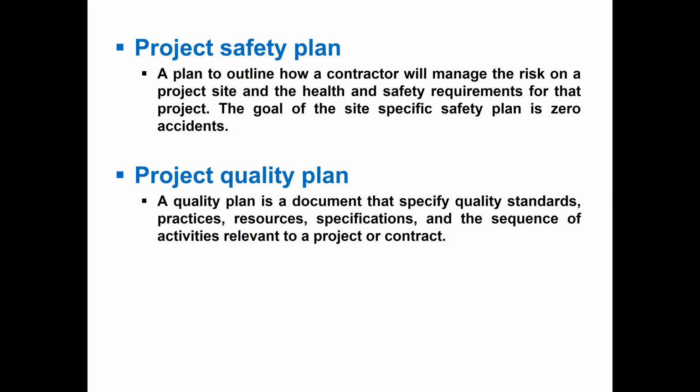It means we should have a safety organization, where there could be a safety manager on site, safety engineer, safety supervisor, and then arrange for the labor force personal protective equipment like helmet, gloves, vest, safety shoes, safety goggles. Then provide proper training to the workers; each worker should get orientation training and job specific training. All these things are part of our safety plan, including how to identify hazards and how to manage those hazards so that no accident occurs. So we should implement physical conditions, housekeeping, and a safety management system on the site. Our safety plan should cover all these things when we prepare a safety plan for the project.